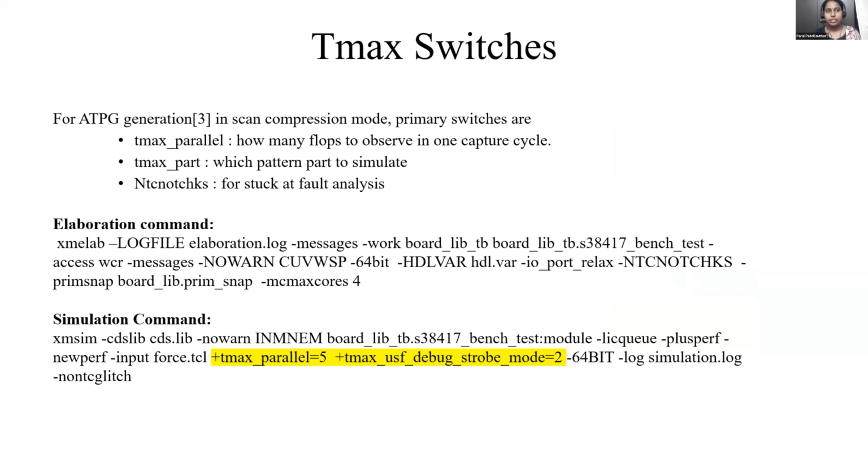We have a certain combinational delay, and we will give a certain sequential delay, but these will be fixed throughout. To check timing delays, like for a wire or a flip-flop, there is another kind of testing, which is called transition testing. But here we are focused on stuck-at. So we will just give that for combinational logic this much will be the delay, and for sequential this much will be the delay, the minimum delay that we should consider.